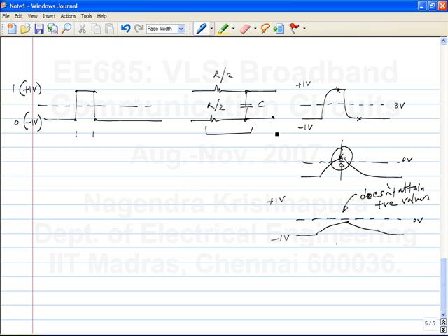Now here we saw that how bad the problem is depends on how much the RC time constant is, or alternatively how much the cutoff frequency of the filter is. Okay, so basically we will see that it is related to high frequency attenuation. So if you have a very large time constant or a small cutoff frequency, then you will have bigger problems transmitting digital data, right? So this will be a problem for everything. To transmit data over any pair of wires, this can be an issue.